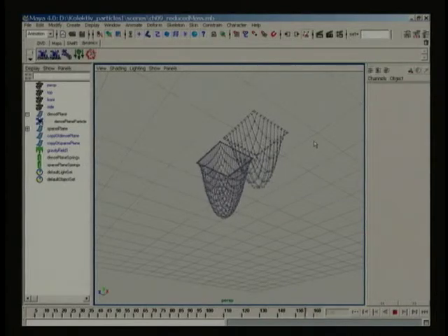Let's look at a real shot which involves softbodies. When working with softbody dynamics, I prefer to balance control by using a blend shape to toggle between keyframed motion and dynamic simulation. In the softbody technique that follows, you'll learn how to spread control over multiple deformed objects, be they blend shapes or nonlinear deformers. This technique gives you greater control over the final result, as you are able to simply dial in and out the amounts of dynamics you want.